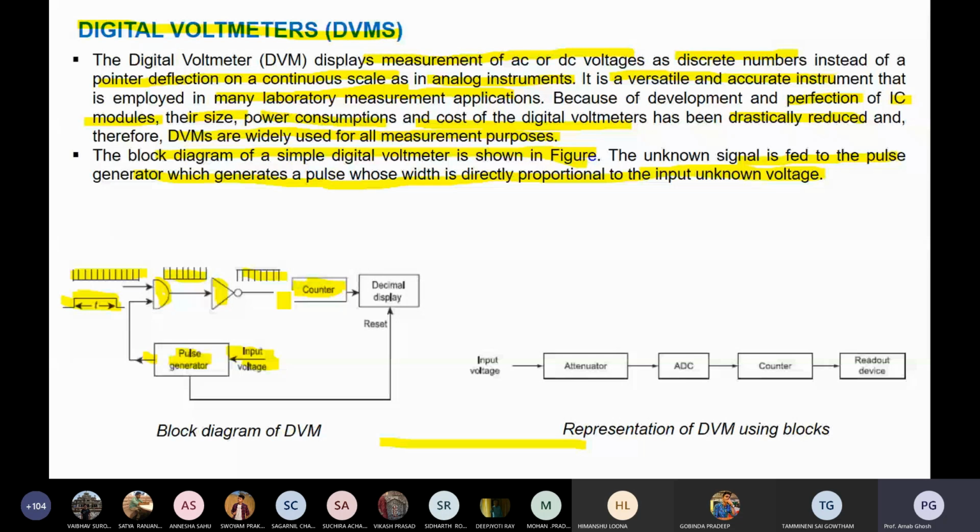Big pulses are there, and that pulse is multiplied, because the AND gate is there, with very high frequency discretized signals. After multiplying you will get signals whose width is the width of the pulses. The rest of the portion is totally zero. Before the pulse it is zero, after the pulse it is zero. So only that thickness remains, the thickness of this pulse.